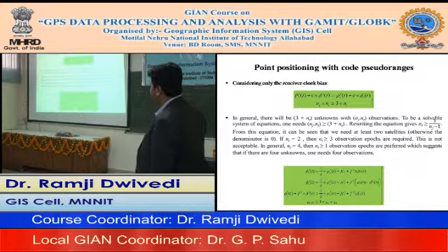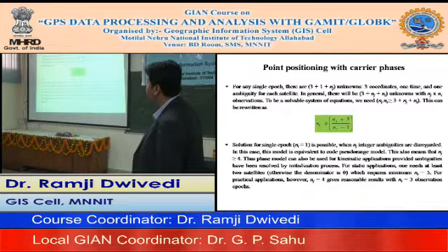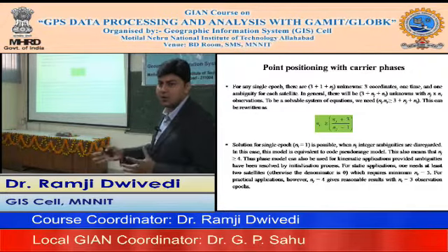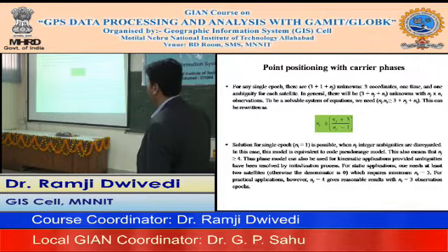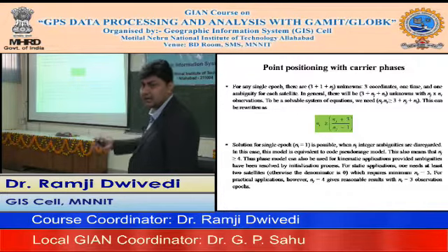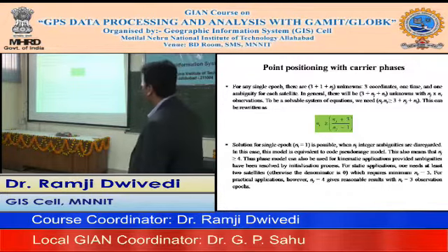So 3 plus Nj plus Nt, again we will go for this relationship. The Nt should be greater than Nj plus 3, and what if we put the minimum number of Nj, that is 2, so for 2 satellites we need more epoch observations, and that's very straightforward because of the number of unknowns and the relationship with the number of observables. So here we'll increase the number of satellites for a particular epoch. So the moment you increase your satellites, eventually the epoch observation also gets increased.